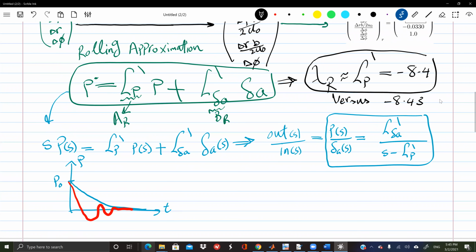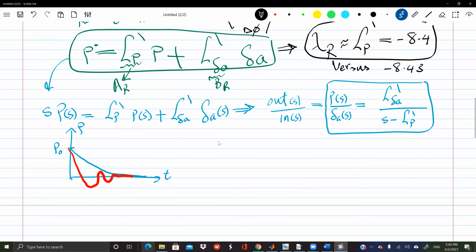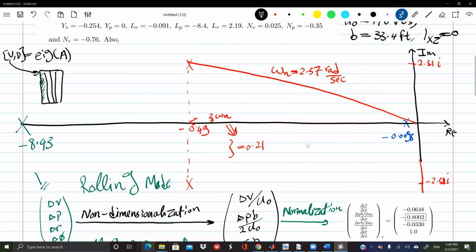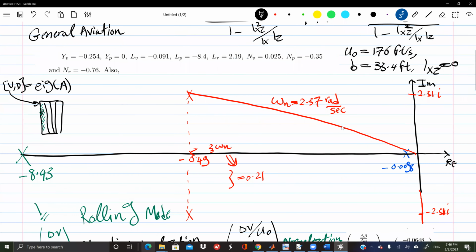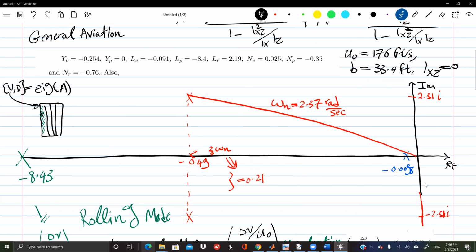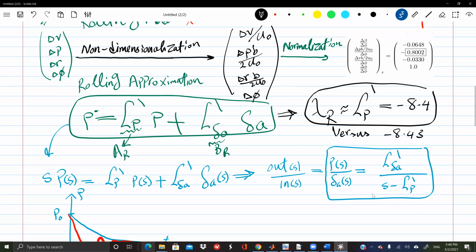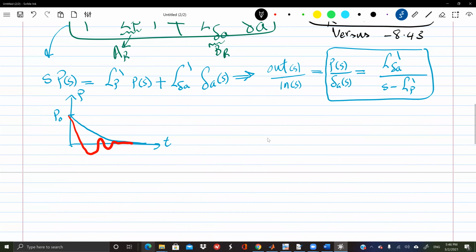In order to get a transfer function, we need to turn the differential equation into its Laplace transform. It's basically a study of the frequency domain instead of time. That's a good question. S is not exactly the frequency, but it's very related to the frequency. When you put S equals j omega, so when we focus on the imaginary axis, then we go into the frequency domain. So in this transfer function, if you put S equals j omega, then we are in the frequency domain. But S itself is not the frequency domain; it's very related to it. Oh, that's interesting. Okay, thank you.